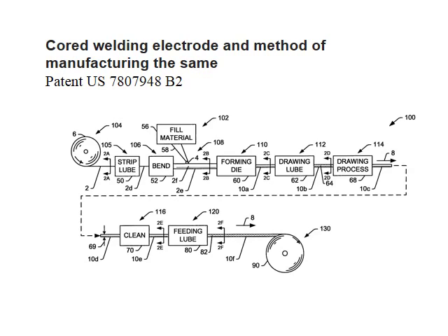The flux-cored arc welding process is made possible by the design of the electrode with a flux contained in the drawn metal tube. Basically, this is shielded metal arc welding inside out and coiled on a spool. This inside out electrode consists of a metal sheath surrounding a core of fluxing and alloying compounds.